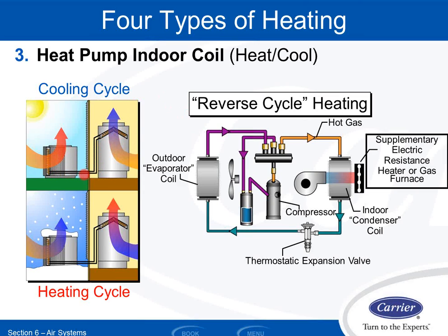Now, I know I said before that heat always goes from hot thing to cold thing, and that's true. But with the refrigeration cycle, I'm able to kind of play the game here a little bit, and I'll explain to you how it works. But in this case, I'm actually able to move the heat from the hot thing, which is your house, and dump it into your yard, which is an even hotter thing, right? It's 75 in my house, 95 outside, and I'm able to move the heat from inside to outside. And refrigeration and pressure is why that works, and I'm going to go through that with you. But for right now, just know that we suck heat out of your air and we dump it into your yard. And we're going from the cooler room and dumping it to the hotter outside.